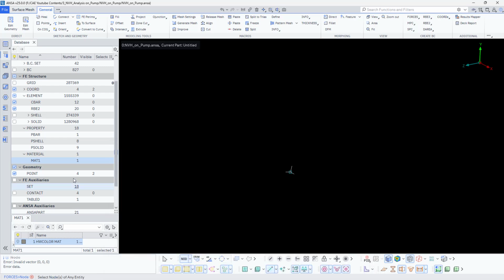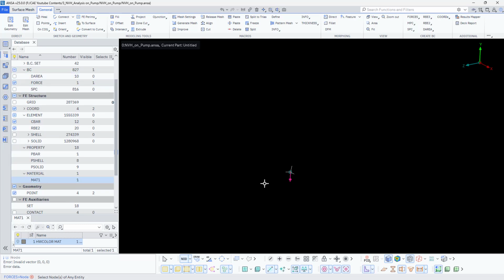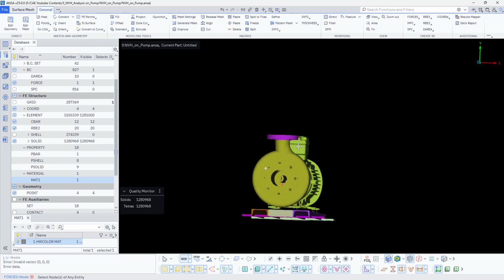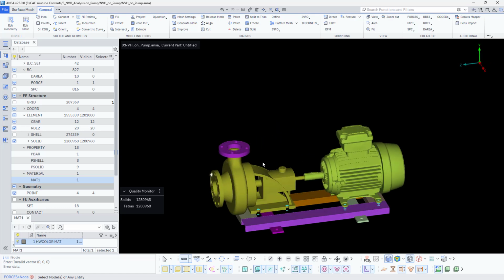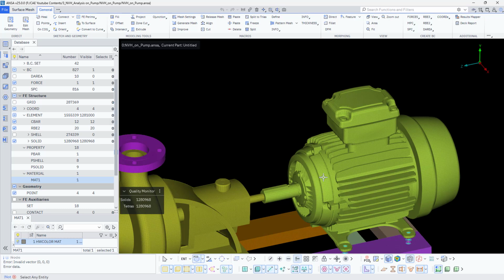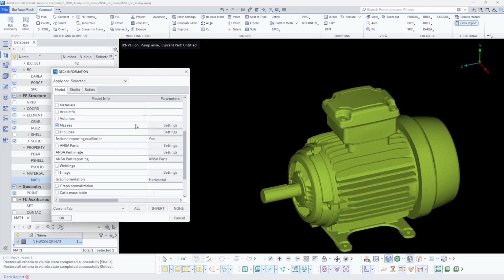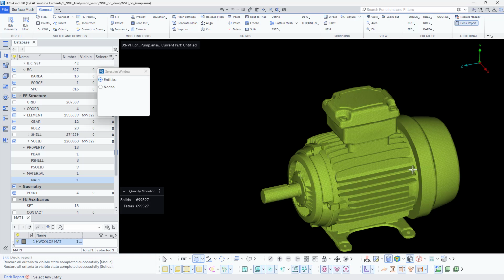I just want to check how the self weight is impacting the supports, the supporting mount and the plates which we have defined. You can see I have defined it along Y. This is fine. Similarly I'll do it for motor 2. The motor point is this, so I need to again check the mass of it. I can just isolate that particular motor. You can see where we have defined it, it's fine. The PID I'm just isolating. So, deck report, mass, this is the entity I'm selecting.